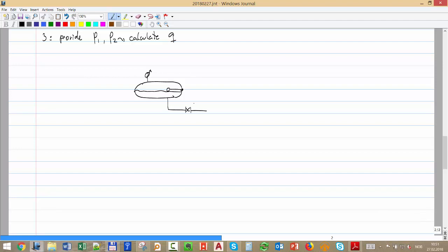And you have two lines, two valves that are controlled by these controllers. So if the level starts going up too much, then that valve is going to open and make it go down. Or if the pressure is increasing too much, that valve is going to open and take out some gas. So you have this control mechanism that is always making sure, it's not exactly like that, but we have a box in between. Okay, we have the control system.